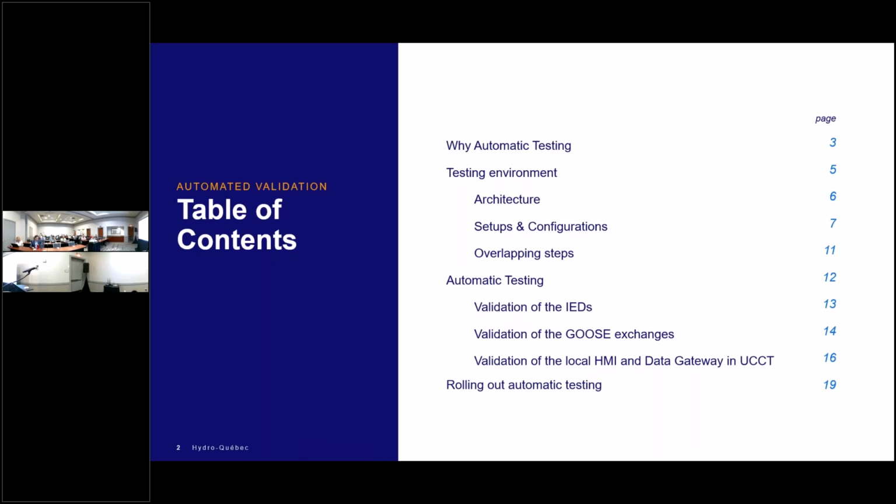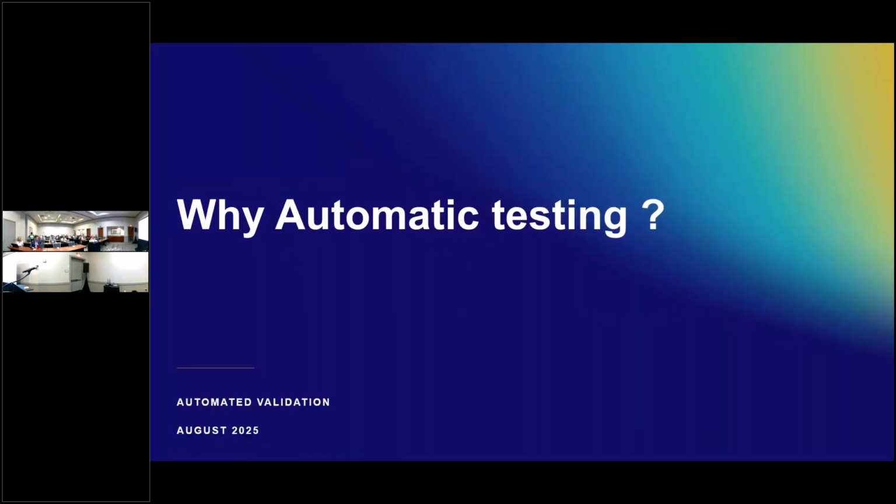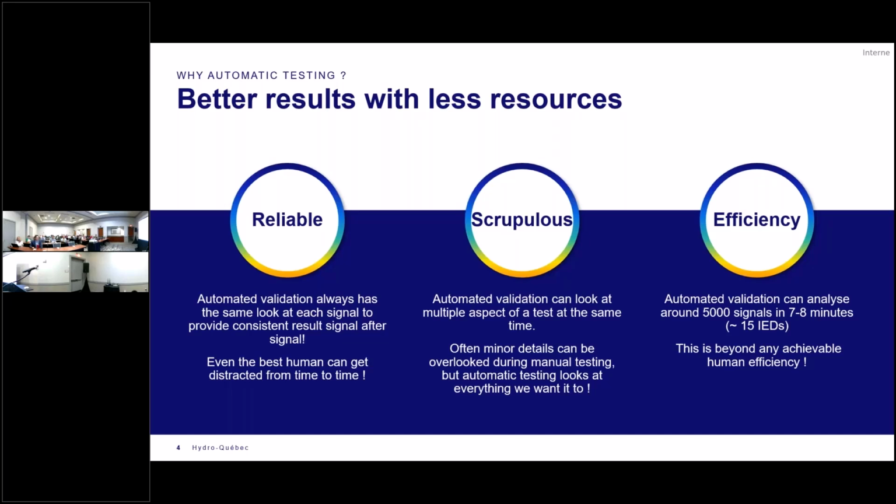We implemented the 61850 using a common data model, a new data model with new protection philosophies, combining the control and the protection within the same equipment in order to simplify the different IEDs that were used, simplify the network, as well as merging the different functions that we have for the station functions, mostly the local automations, the HMI, and the gateway.